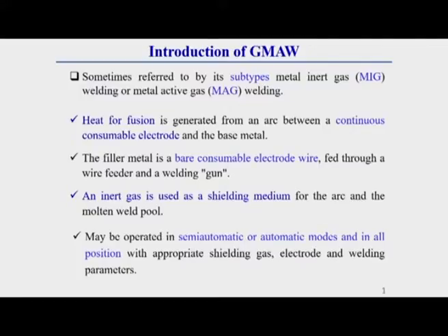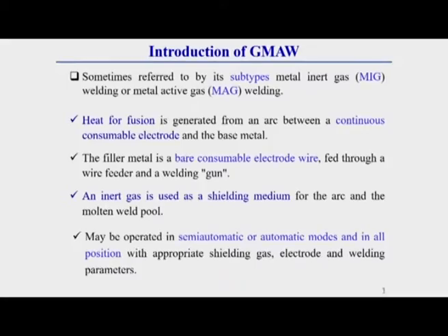MAG welding means metal active gas welding, because the shielding gas which is used to protect the molten pool and arc, if that gas is active in nature, then that is called metal active gas welding. If an inert gas is used as the shielding medium or shielding gas, then that is called the metal inert gas welding technique, that is MIG welding.